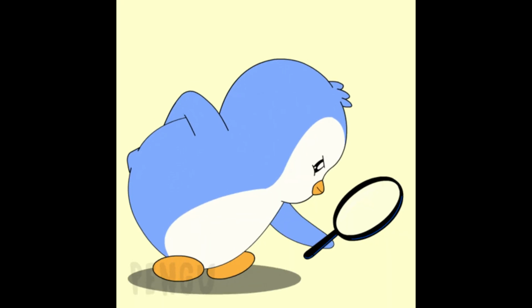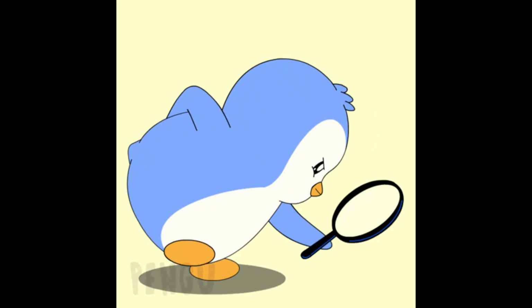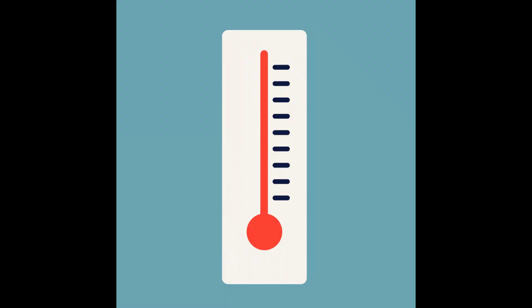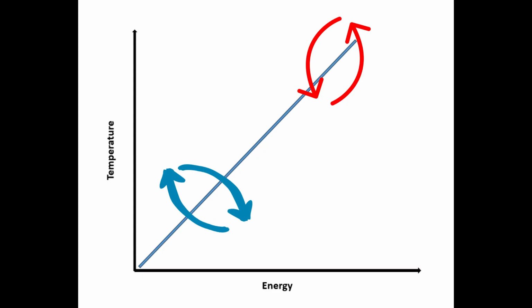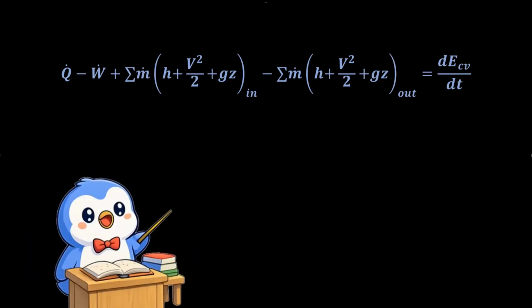So now the next question is the big one. What actually causes the temperature separation? Why does one part get hot while another part gets cold? The short answer is that energy is being redistributed inside the tube. The higher pressure rotating outer flow gains energy. The lower pressure inner returning flow loses energy, and because of this, the outer flow becomes hotter and the inner core becomes colder.